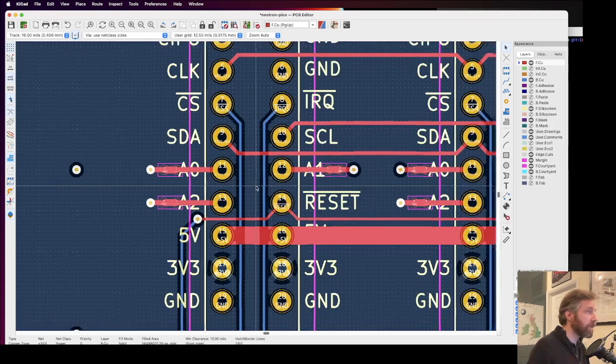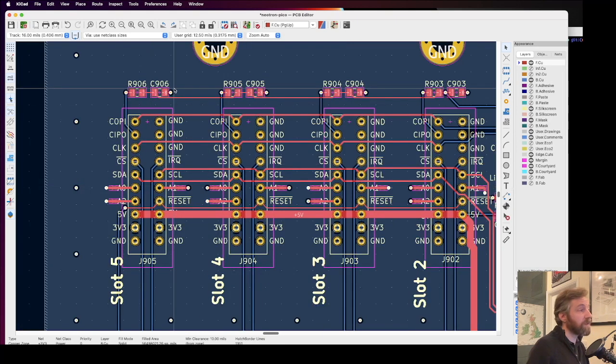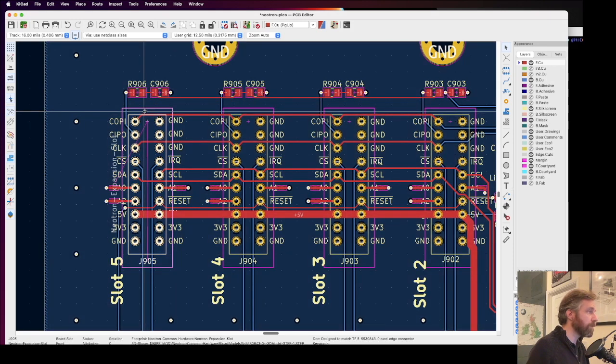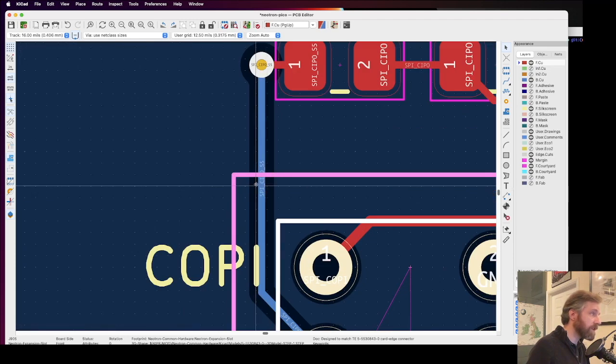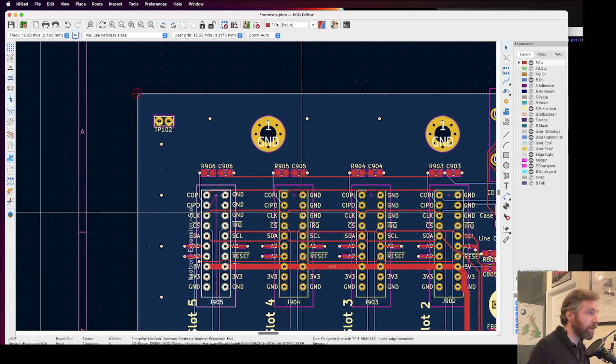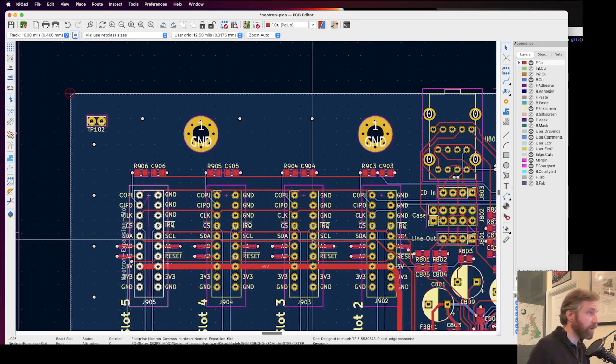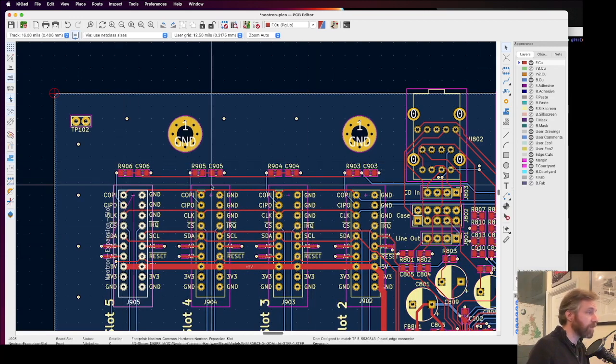Yeah, that one seems fine. Traces. It's mainly these net ties, the vias I moved around. Previous version of the board, these parts up here were far too close to the slot. I didn't check the 3D model carefully enough, and so what happened is when you went to solder the connector down here, the leg of the connector actually sits right about here, and that's where the components were. So that didn't work. I had to chop the leg off my connector. It was still soldered down okay, but I had to chop the leg off to avoid fouling that resistor.